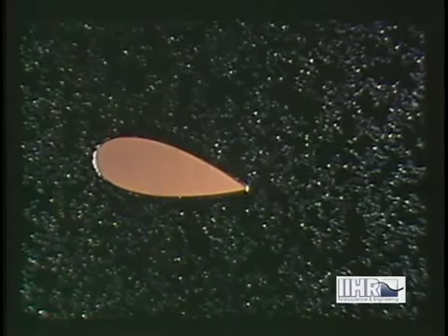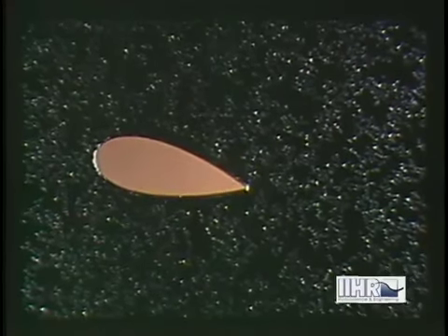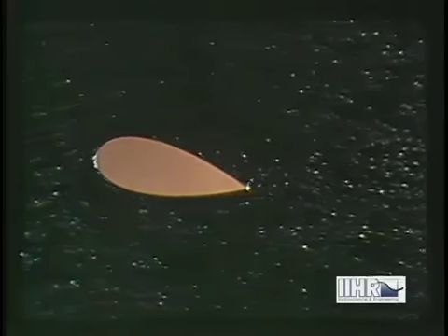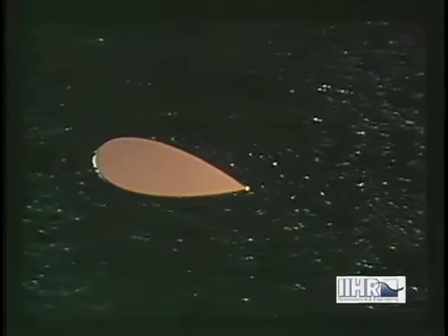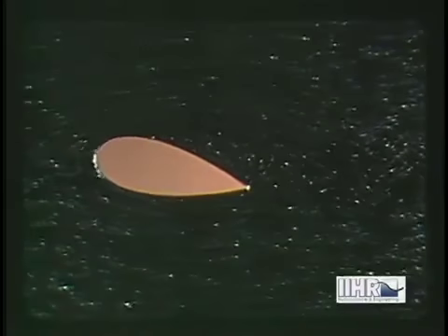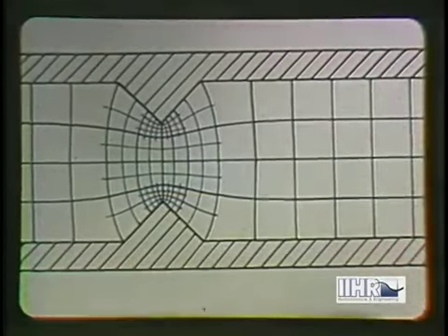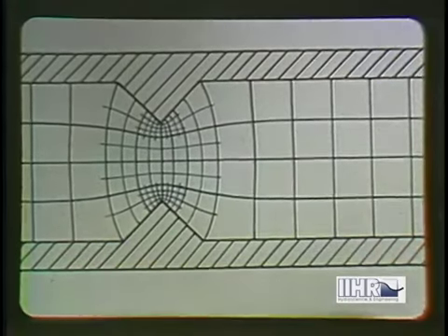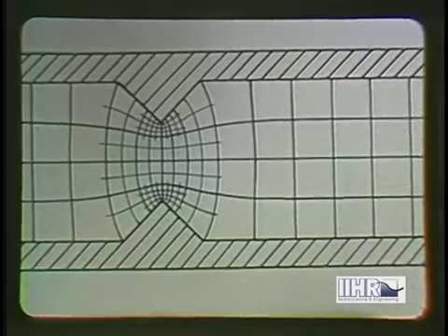One reason for the failure of a fluid to move according to the flow net is the phenomenon known as separation, which occurs in boundary regions of too rapid deceleration. As we shall see in a subsequent film, such separation is often the result of appreciable rotationality due to viscous shear along even a smoothly curved boundary. A type of separation which is of interest now is that due to boundary angularity. The flow net for a sharp boundary angle would call for an infinite velocity at the corner, which is physically impossible.